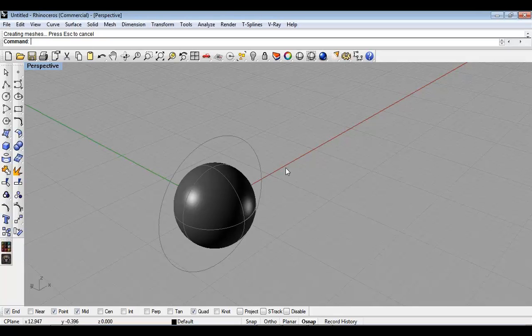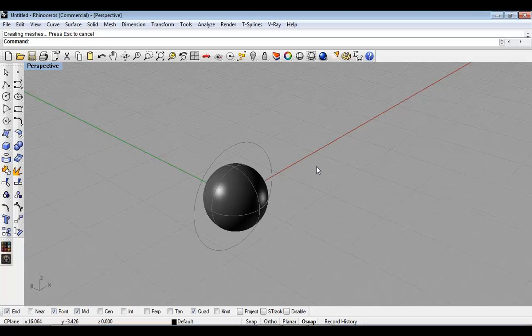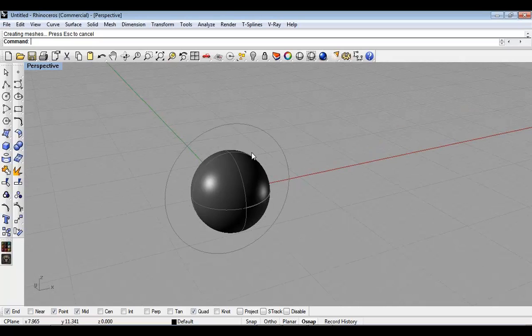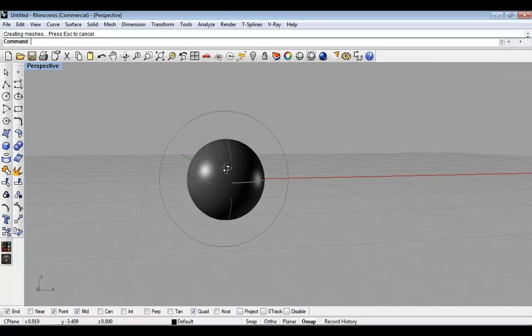And the fit has to be reasonably perfect, because when it's hollow, the jewelers out there know that if you cast something hollow and you bend it too much, it has a tendency to want to split or crack. So how to make it was an interesting question.